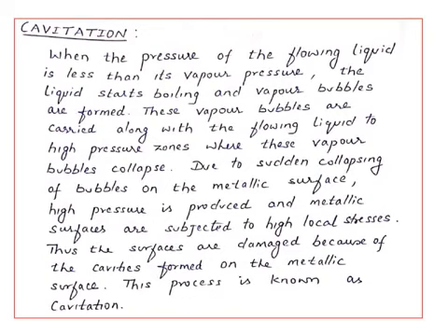As I was discussing in the turbines as well as in the draft tube, we have found that at the inlet of the draft tube the pressure is always negative. And also at the runner exit the pressure will be negative. So there is a chance that whenever the pressure of the flowing liquid reaches the vapor pressure, vaporization of the liquid takes place. So the liquid starts boiling and vapor bubbles are formed.